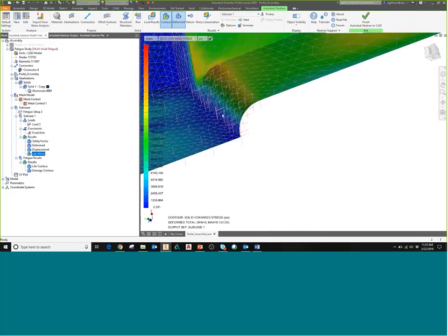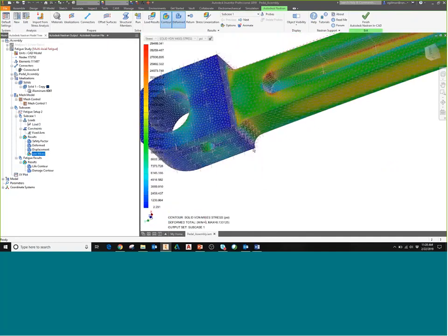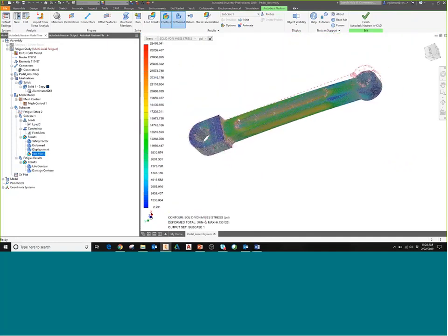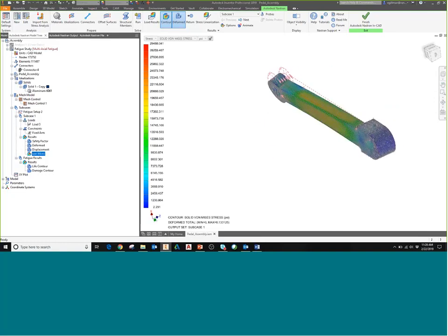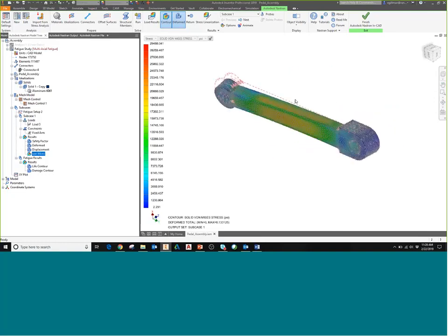I'm also going to see some stress increase along the lower fillet of my crank arm near where it's being fixed as well. In general, if I just look at this with linear static analysis, I'm only hitting 29,000 PSI, and the yield strength for my aluminum is about 40,000 PSI. So I'm below the yield strength of my material. I would assume that this isn't going to fail. I have a good cushion there and a good safety factor where I'm pretty comfortable with running this and sending it out. But if I'd like to see what I could expect as this is loaded over and over again,